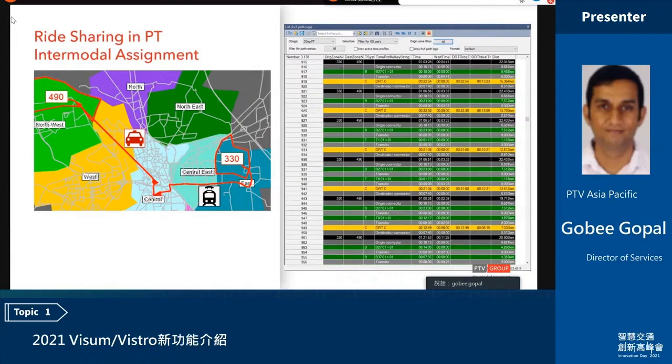Then the second step is we apply these average detour factors to the ride sharing links. On the right side of the screenshot, these are the PuT path links which you can define, and perform a new route search or route choice using the updated travel times. So this goes around many iterations and takes some time. Multiple iterations are required, and at the end we have a well-converged detour factor, but if we restart the assignment, we could not use that as the initial value.